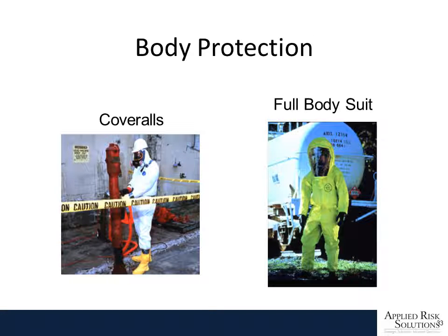Body protection should also be worn by anybody that's at risk of being exposed to a large spill of chemicals. This would include times of unloading chemical tankers or anything like that. Several different types of chemical exposure suits are available. You have coveralls made from Tyvek, and you also have full body suits that would provide good protection in the event of a spill of a really hazardous material.